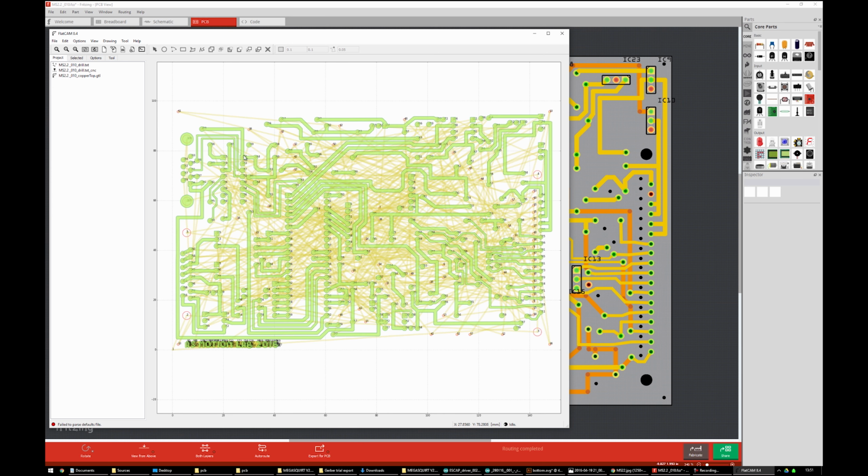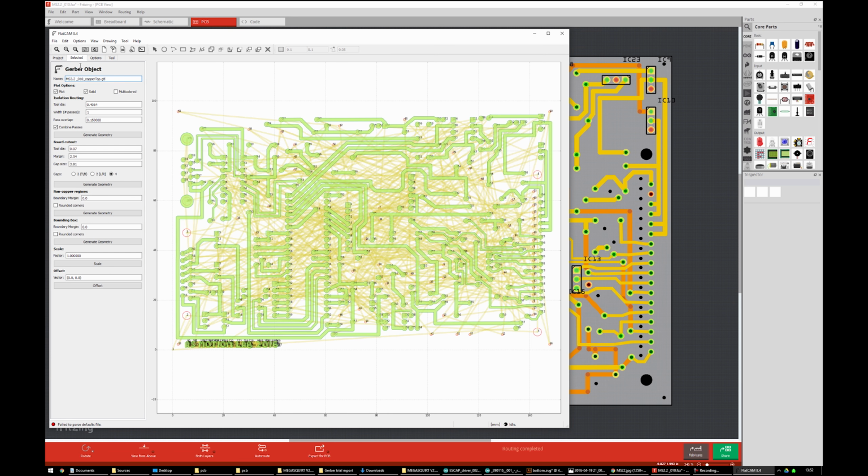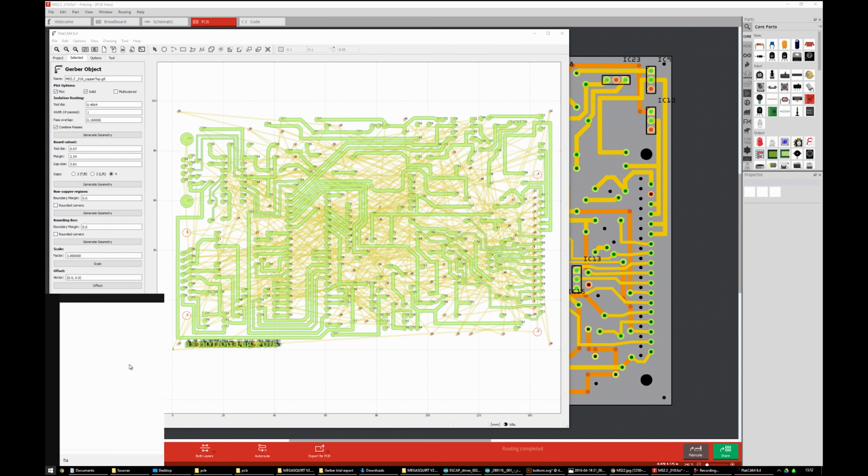And work out the toolpaths. So we first of all select the input file, which is the copper top GTL. Now with this selected, we want to first generate the geometry. So you need to make sure these settings are correct. Now I can't remember, I don't have a preset template for this written down. So what I usually do is use the last project which I know worked really well. So I'm going to open up another FlatCam.